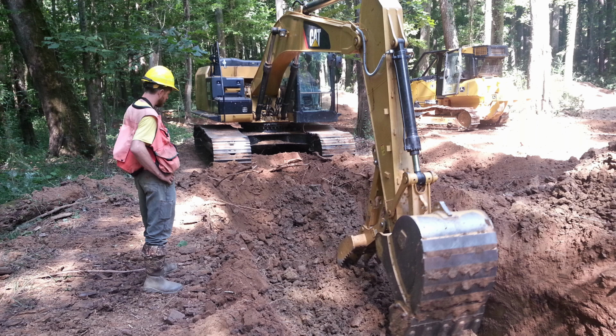It's very important to stand by and to watch carefully as the excavator operator digs the core trench for the groundwater dam. This is because the operator has trouble seeing the bottom of the trench and would appreciate your assistance in deciding what soil to remove and what soil to save to build the groundwater dam.